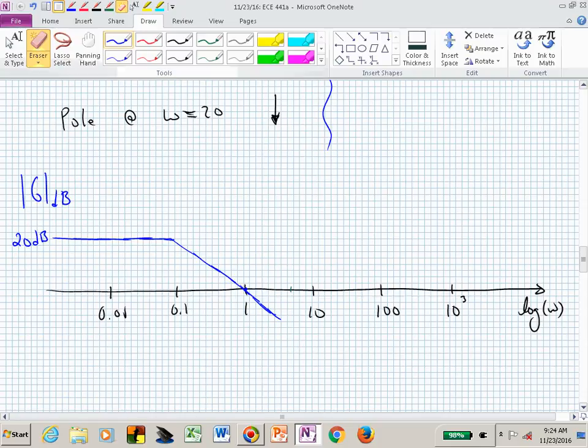And now I can erase that, and I can come down with that same slope. But then once I hit 5, now I'm going down at 20 dB per decade. I now change my slope to introduce a plus 20 dB per decade. Now I'm flat again in terms of my magnitude. And how long am I flat? Until somebody tunes me? Never mind. A little musical reference there. But this is flat in magnitude. I now am going to be flat until 20.